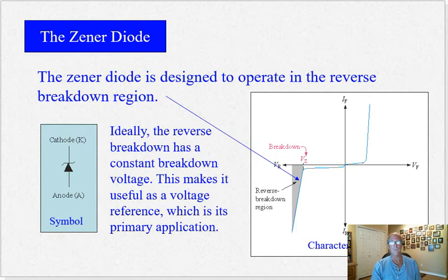We start out with this Zener diode. And the Zener diode is used for voltage regulation primarily. It's operated reverse biased, okay? So the positive terminal of the supply is connected to the cathode, which results in a breakdown region here. All right, this is where they're operated.